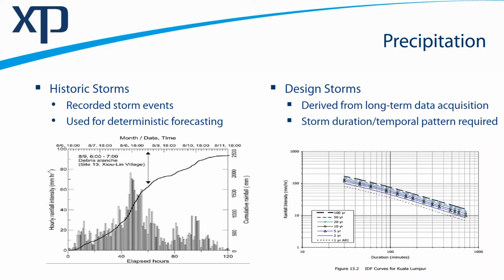Different countries use different terms, so Australia, for those who are not familiar, really is moving away from average recurrence interval as a terminology point. It's now moving to annual exceedance probability. They're functionally the same, but it makes it very difficult for the 2-year event, which unfortunately is something like the 63.4% AEP, but that's just statistics.